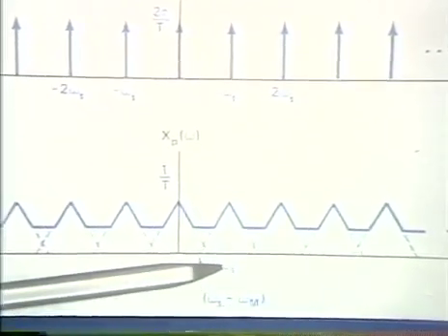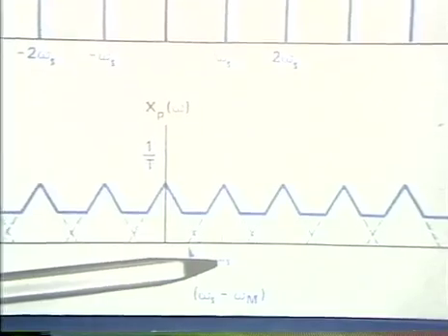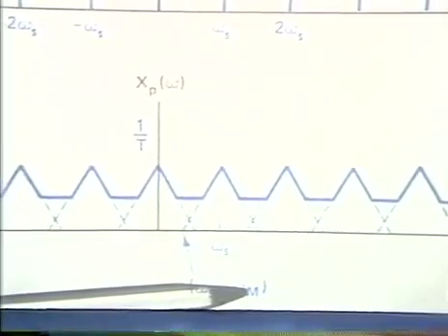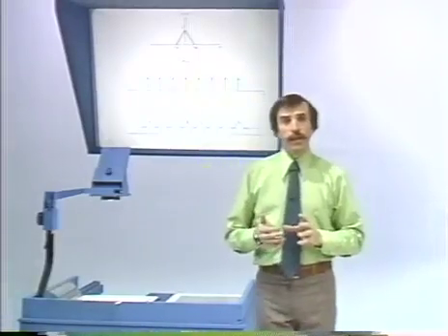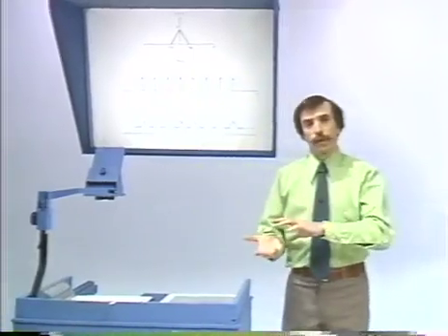In other words, the sampling frequency is not greater in this case than twice the highest frequency. So what happens here is that, in effect, higher frequencies get folded down into lower frequencies. What would come out of the low-pass filter is the reflection of some higher frequencies into lower frequencies. As I suggested a minute ago, that effect is referred to as aliasing.